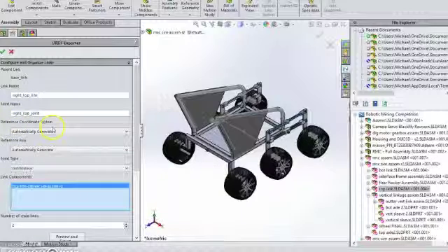So the reference coordinate system and the reference axis usually should be set to automatically generate. I haven't found great success with forcing an axis or a coordinate system in, so it's best to try to make your assembly fit how it should be so that these coordinate systems and axes will automatically generate.